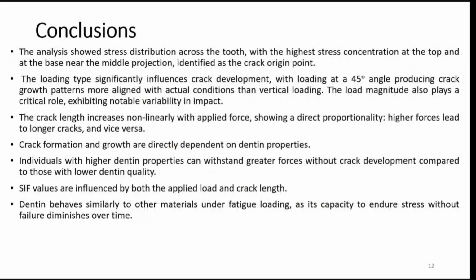Conclusion: the analysis showed stress distribution across the tooth with the highest stress concentrated at the top and at the base near the middle projection, identified as the crack origin point. The loading type significantly influences the crack development, with the loading at a 45-degree angle producing a crack pattern more aligned with actual conditions than vertical load.